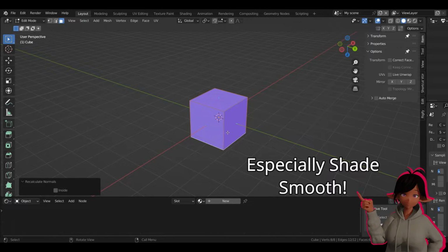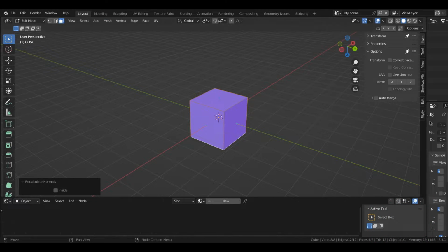When I'm modeling, I may stop and recalculate the normals outside if I feel like experiencing some shading issues. Blender is really good at recalculating normals, but in the off chance that Blender misses a face, we can click on it and then click recalculate inside, since essentially what that'll do is flip it no matter what.